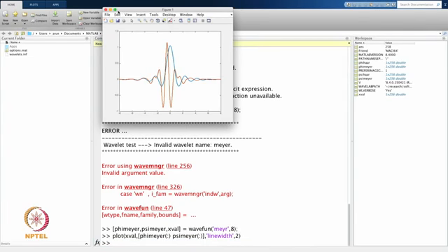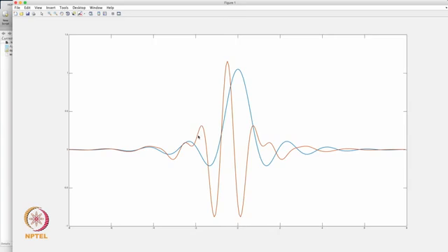So, this is how it looks. The scaling function, shown in blue, and the wavelet function, shown in red, both belong to the Meyer family. It is clear now why the scaling functions or the wavelet functions from the Meyer family do not have a compact support, because they only die down exponentially. Consequently, the filter coefficients associated with this are not going to be of finite length. That means they are not FIR filters.